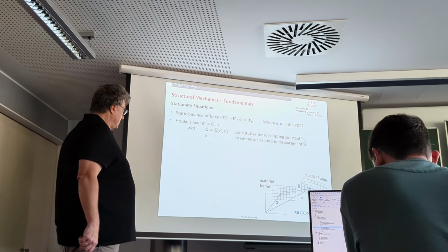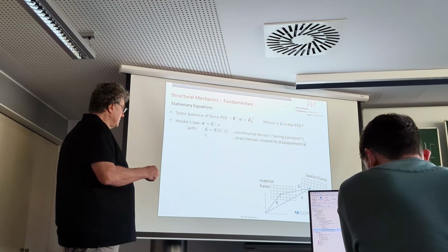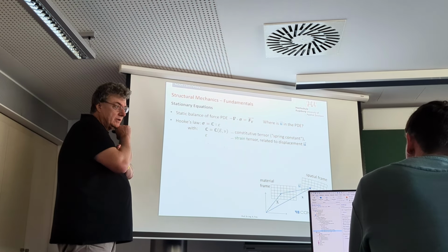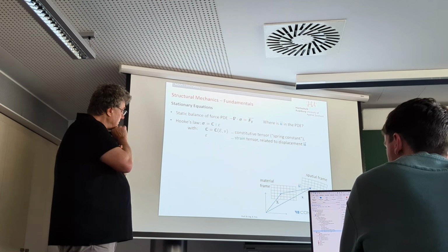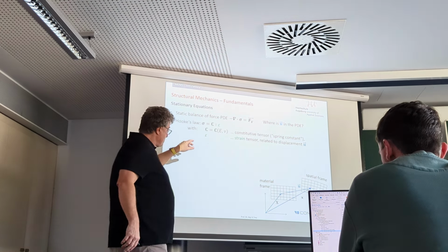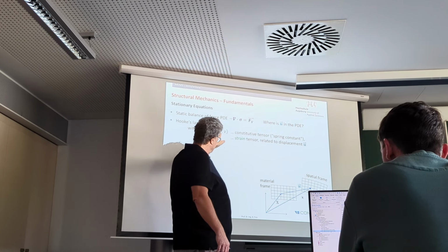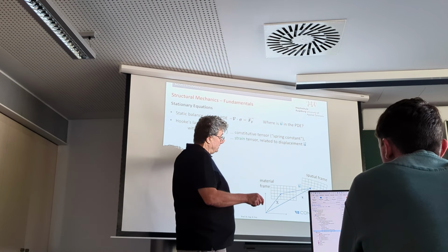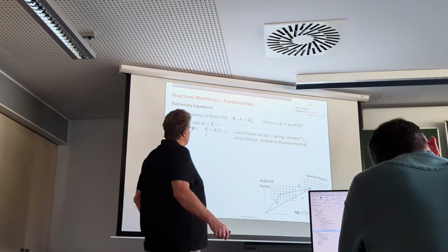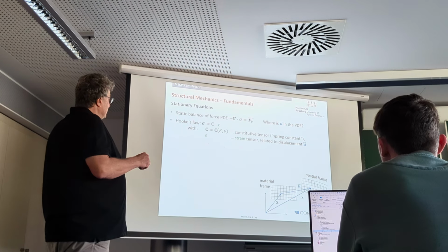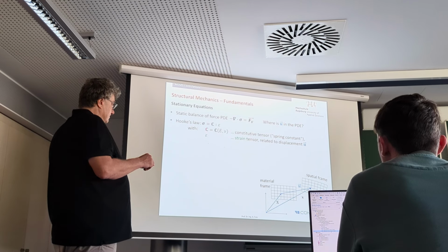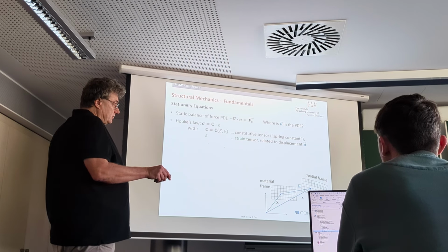I will show you later how that thing looks like. I mean, if it's 4 dimensional, you cannot even display it. So there is a notation, Voigt matrix, you probably heard about that. And in many cases, you can write it more simply. For certain types of materials, at least you get not only the Young's modulus, but also the Poisson ratio. So basically, this is Hooke's law, which relates the strain to the stress. In a very simple situation, it would look like this.